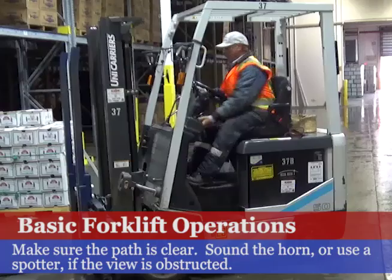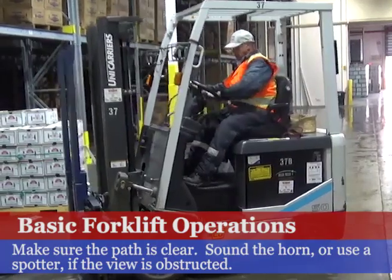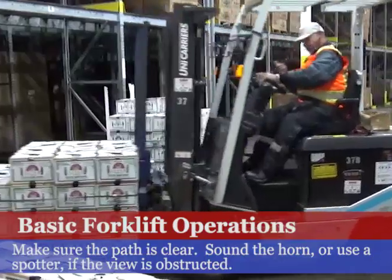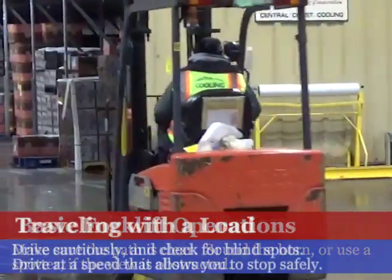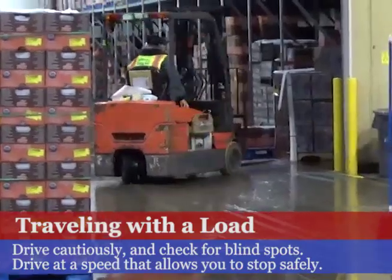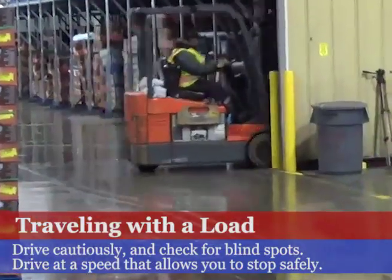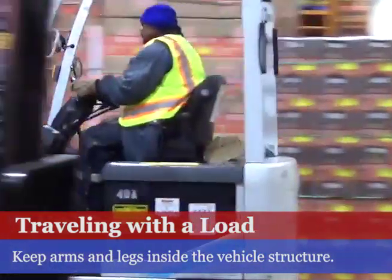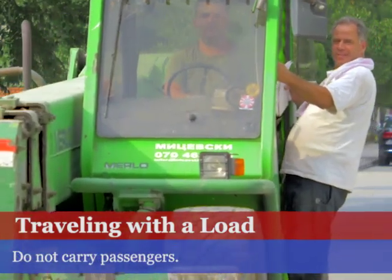When starting the forklift, make sure that your path is clear. Sound the horn, or use a spotter, if the view is obstructed. Drive cautiously, and check for blind spots. Always drive at a speed that will allow you to stop in a safe manner. Keep your arms and legs inside the vehicle structure. Do not carry passengers on the forklift.